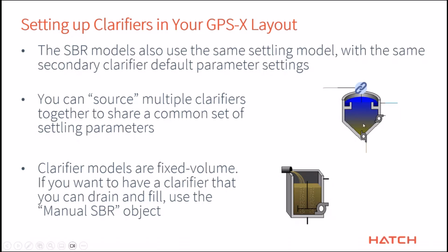Also, I would mention that all of our clarifier models are fixed volume. By that, I mean the clarifier will always assume that it is completely full and overflowing. So if you are in a situation where you would like to pump down a clarifier as part of some simulation and then fill it up again, I would recommend using the manual SBR object, where you can do the same thing. It has the same clarifier model as this one does, and you can control it much better. You can have control over these pump connection points, empty it out, and fill it back up again. The SBRs are designed to have variable volume.